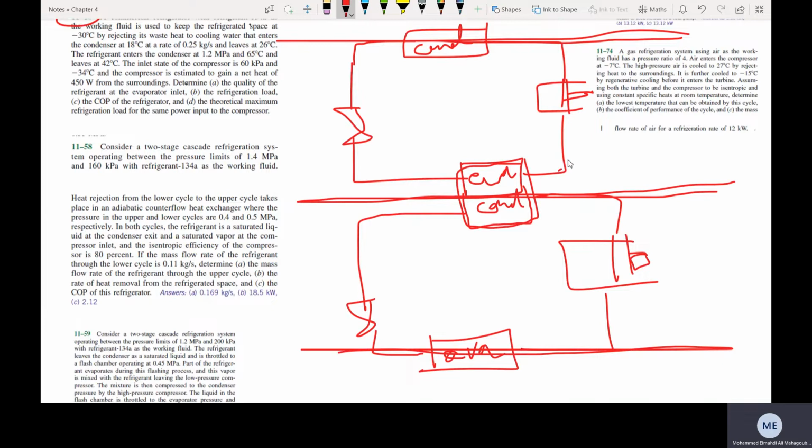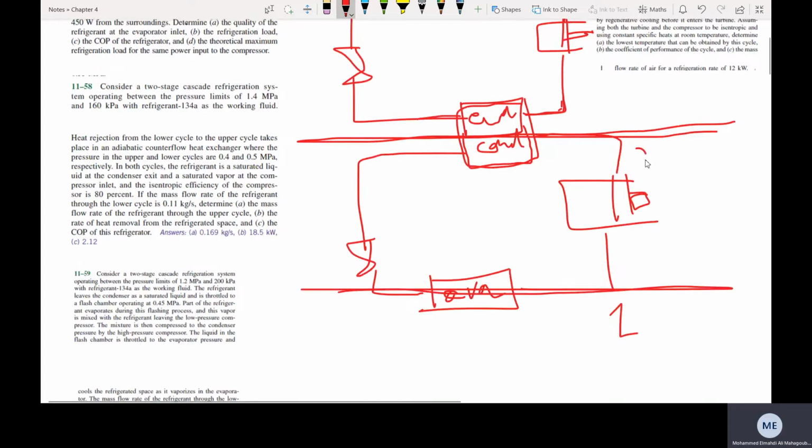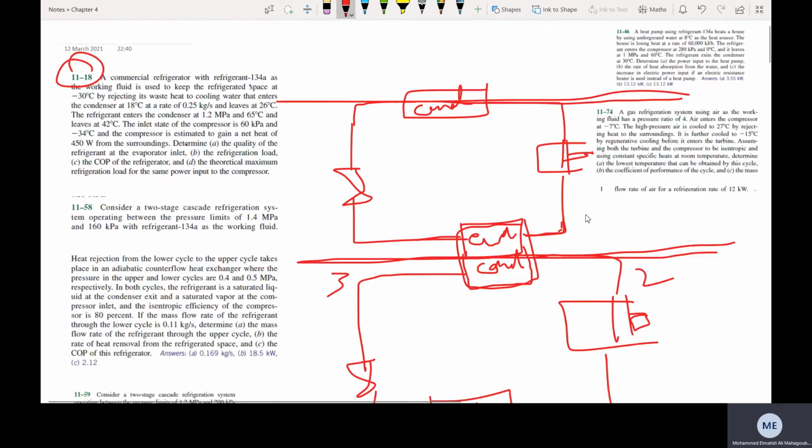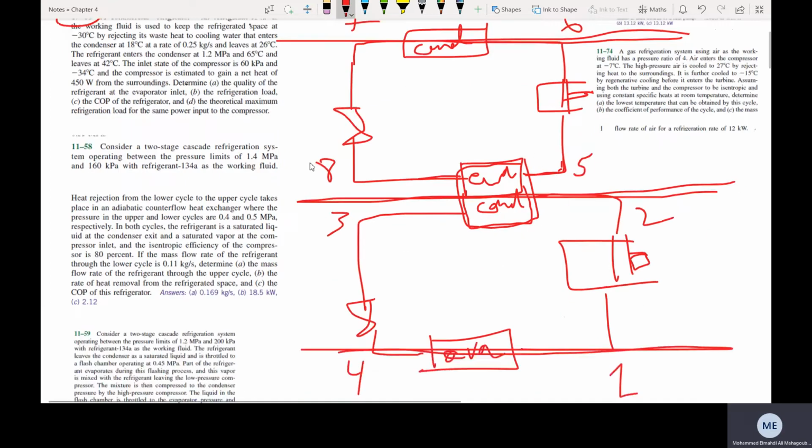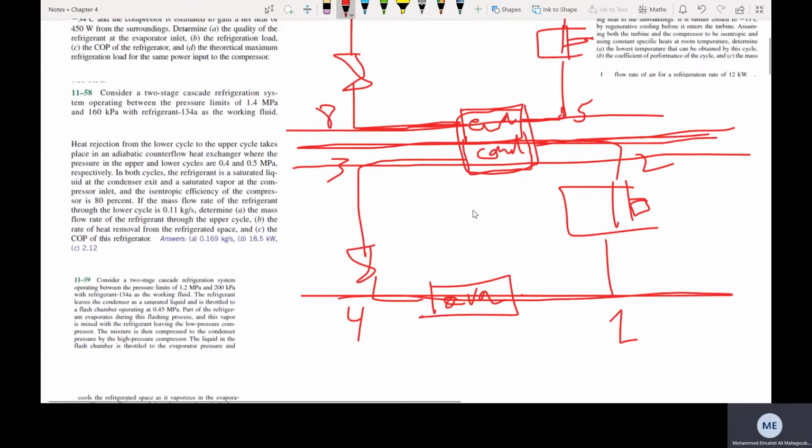So the fluid in this cycle, the lower part here. Let me call the points: this point 1, this point 2, this point 3, this point 4. And now this is point 4, okay, so this point 5, this point 6, this point 7, this point 8. So between 5 and 8 and between 2 and 3, sometimes they can work all on the same pressure. So this intermediate pressure is the same. And sometimes this stream has the high pressure. So I have here first intermediate pressure, second intermediate pressure. So I have 4 pressures in the cycle.